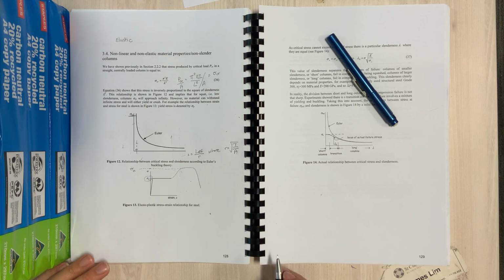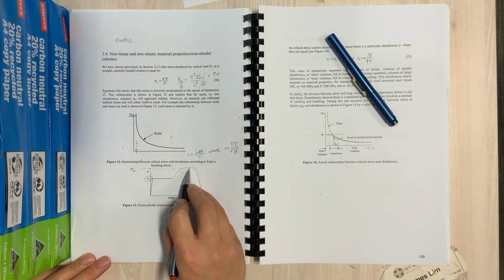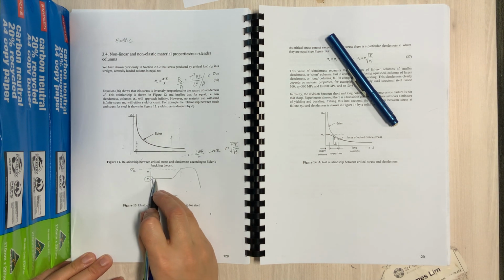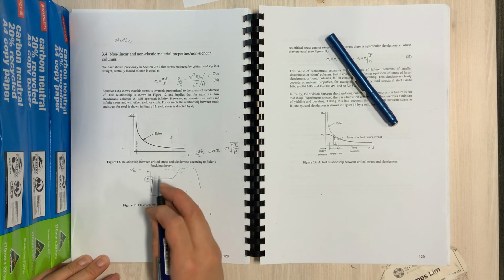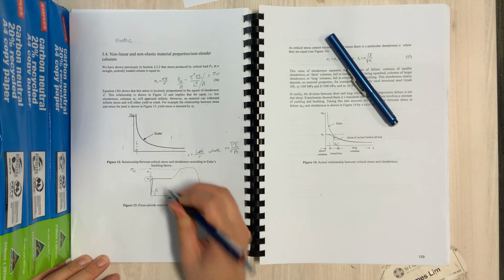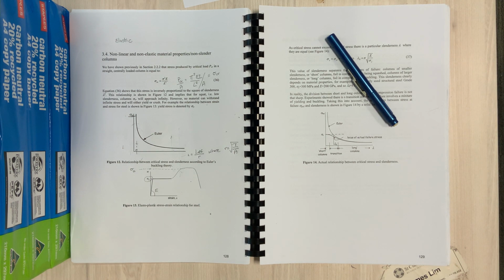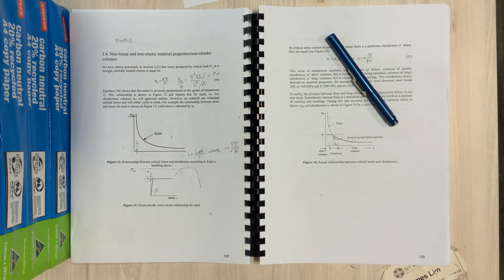We're only concerned with the yield stress because once it reaches the yield stress, even though it does rise up later on, which is one of the peculiarities of steel, along here there's zero stiffness. Here you're moving up with the same stiffness, the same gradient of E, and then when you reach the yield stress, there's a horizontal plateau. So suddenly your material has no strength. It's gone from there to there with no strength at all.